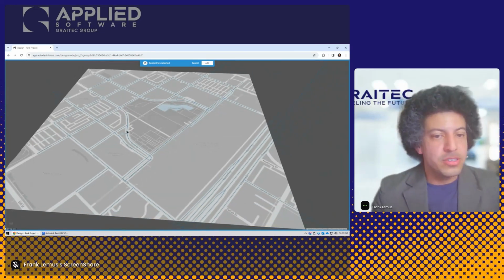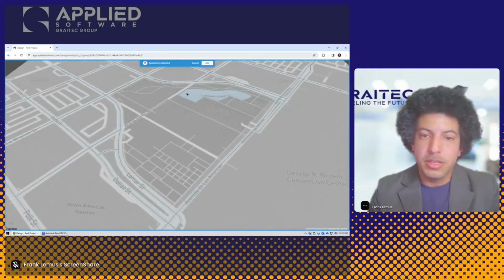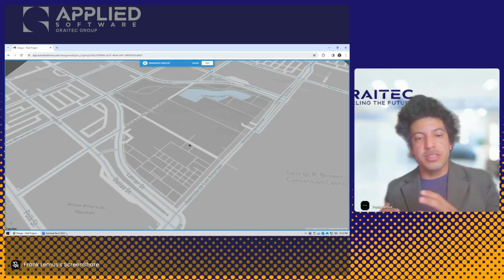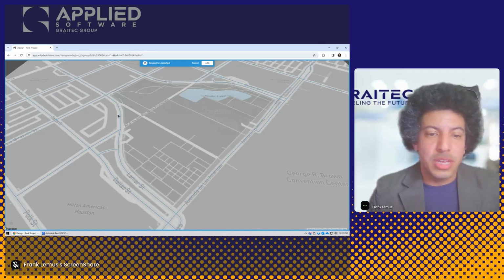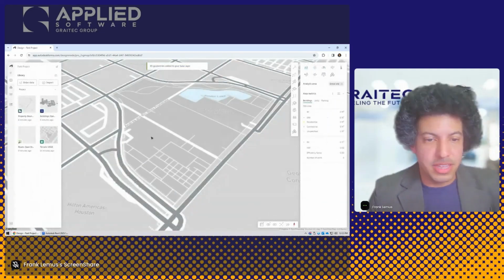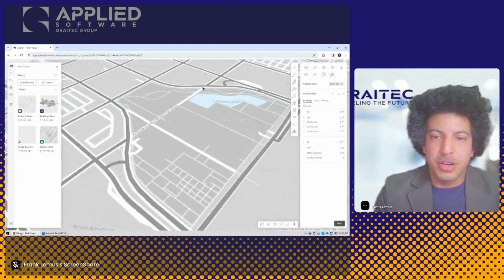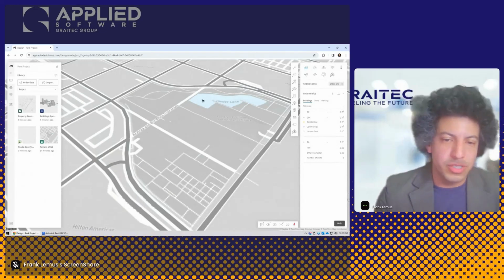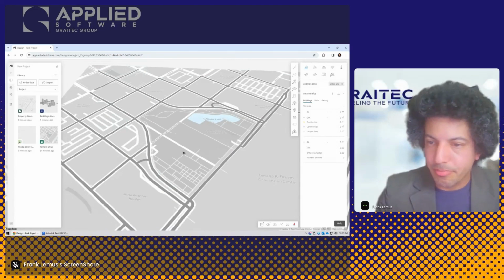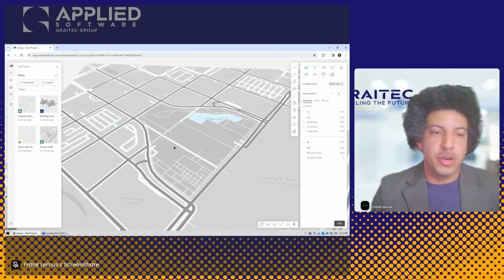But you see that by default, all of the selectable elements are selected. Notice, for example, that this isn't a road. It doesn't read it as a road. Whose fault is that? That's the fault of the road data that we collected. So can we add something there ourselves? Yes, but not here. So I'll say add. That's everything that was selected. And actually, this is not even a road, guys. I'm sorry, this is a sidewalk, but I'm going to add it as a road just as a way to. Same thing here. It's just a sidewalk. It is a park after all. But still, the reason it doesn't register as a road is because the data doesn't register it as a road.